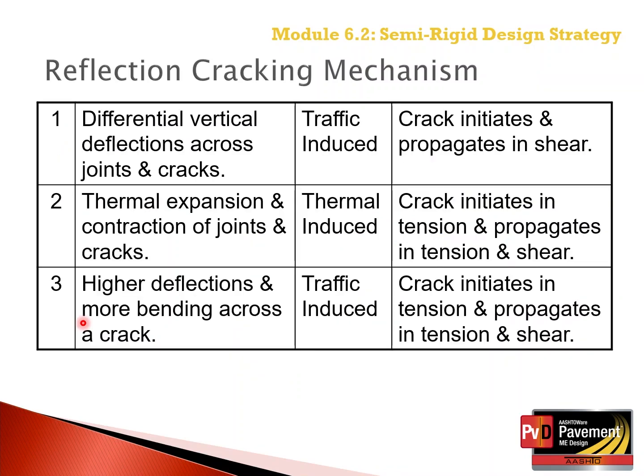And this table simply summarizes what we just mentioned. Mode 1, differential vertical deflections across the cracks. Those are traffic induced. The crack initiates and propagates in shear.